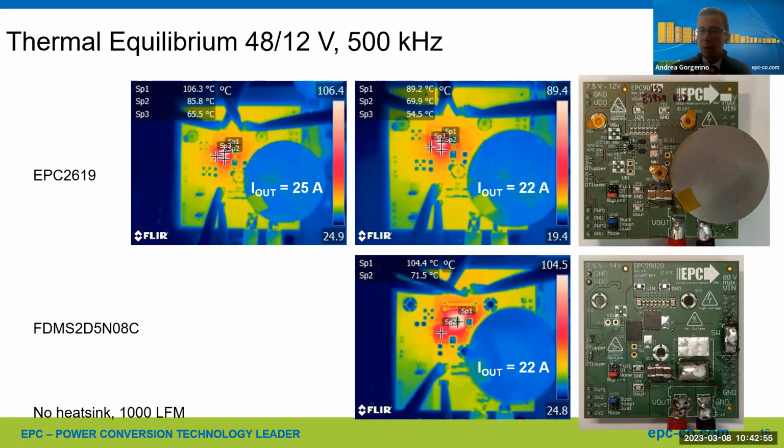The second one is the power loop itself. I mentioned that a little bit, especially for EMI, that contributes to all the ringing and losses eventually. And to do that, we have a lot of guidelines. We recommend, and you can do this really only with GaN devices, we put the 2 devices here next to each other, high side and low side, and the capacitors right here. These are the bus caps. And the loop is basically the minimum physical loop you can make.